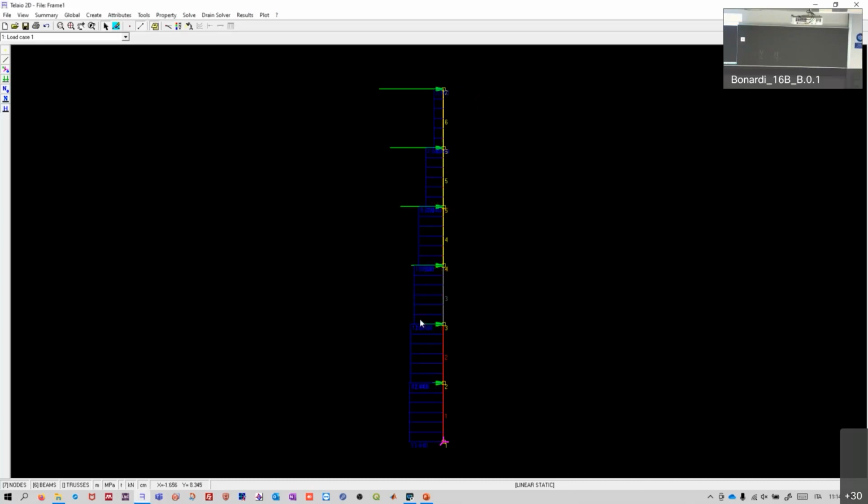And this is the level of the shear force. Okay, people in class cannot see anything. I hope that people at home can see it better. But basically, the shear force is piecewise constant, and it reaches its maximum at the base of the structure, as I said before.